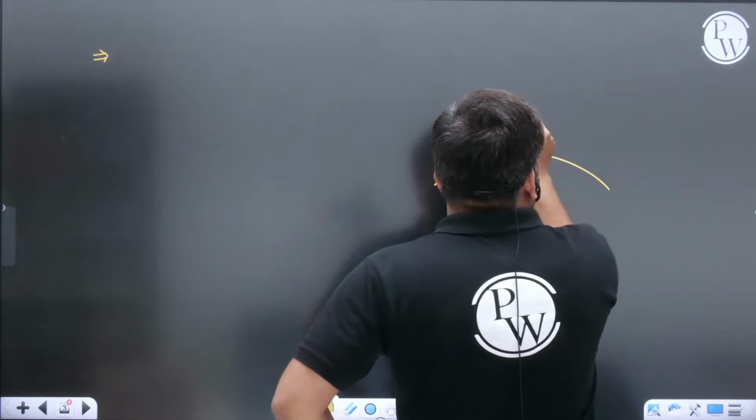And for making the profile of the gear, we have only two options with us. Either you can use the involute curve, or you can use the cycloidal curve. Only these two profiles can be used to make gear teeth. Why? Because only these are the two profiles which satisfy the law of gearing, and all those profiles which satisfy the law of gearing, my dear students, are called conjugate profiles. Getting my point?